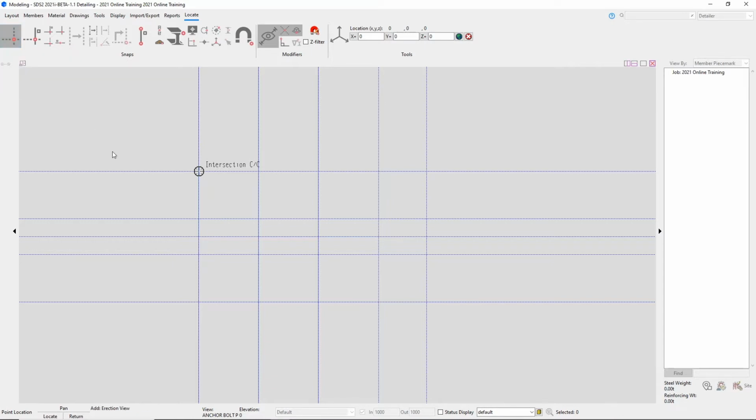So the order in which we pick the points for our grid lines will affect how our views will come out. The points picked for all the views will also be the extents of which that can be opened or that can be viewed when you open that view. So you need to be careful when creating these grid lines, as these will be the extents. So if you would have a member outside of these grid lines, they wouldn't be shown in that view.